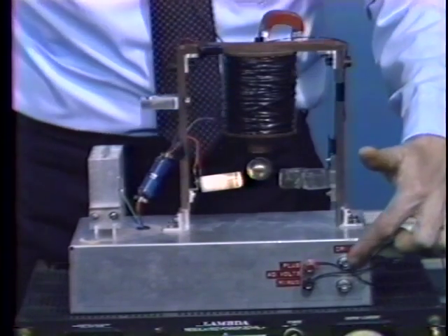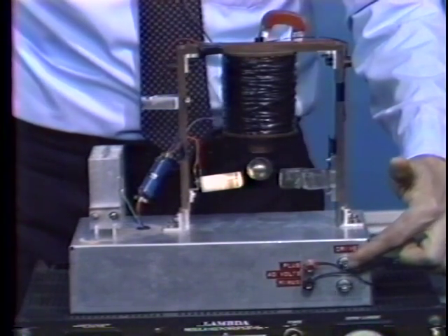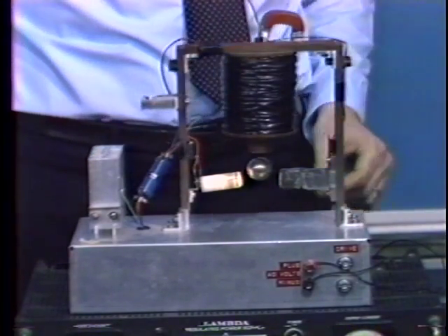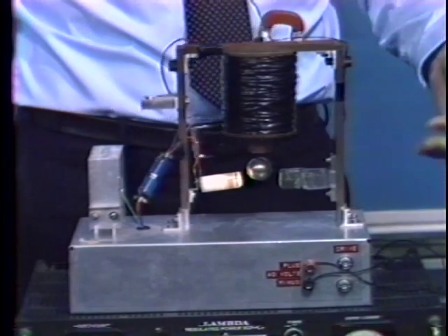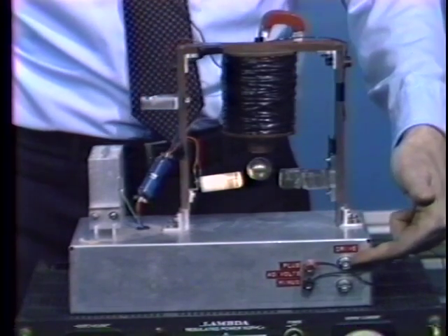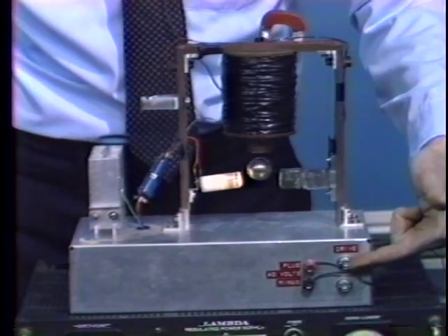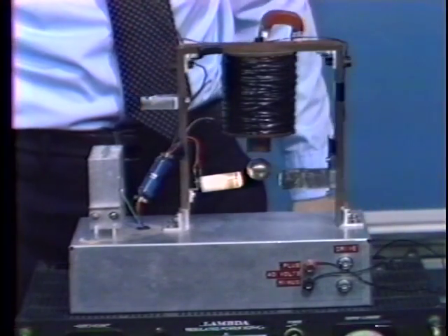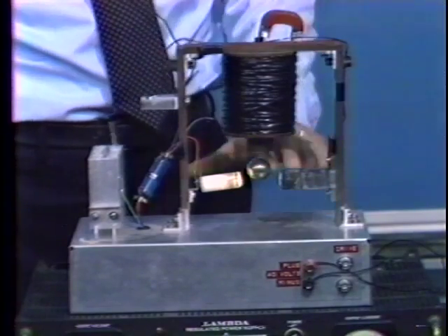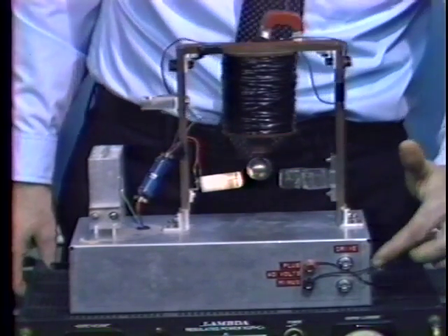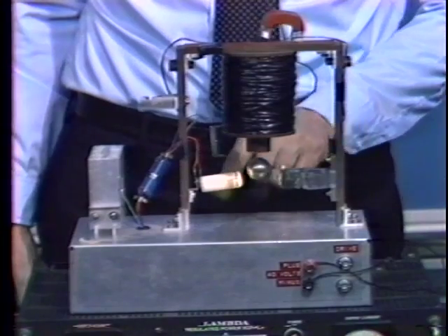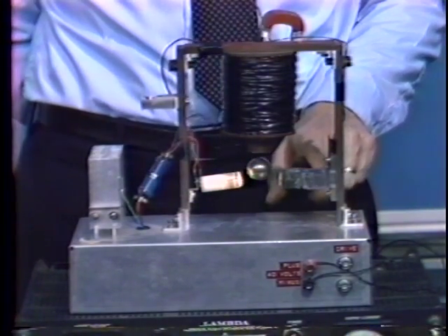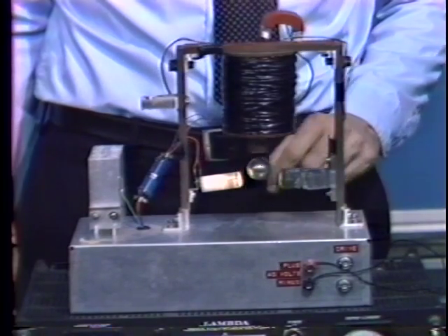There's just a connection basically via a large resistor from the point labeled drive to the magnet current, and so we can then inject little incremental step changes in magnet current by applying a square wave to the drive terminal on the device. At the same time, we can measure ball position. We have an output from the device that gives us an electrical signal proportional to ball position.